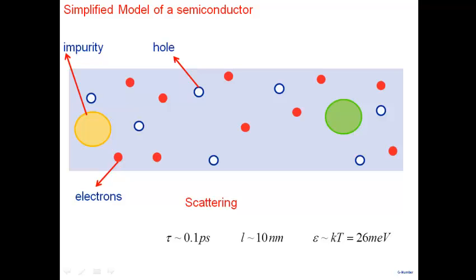It's totally random. Okay. So that's the picture that we have. So if I draw a line here, a cross section here, and suppose I'm interested in current, I've not applied any voltage here, I would expect on an average the same number of electrons which go from left to right as the number of electrons which go from right to left, right? On an average, there's no reason from symmetry to expect that more electrons are going right as compared to more going left here. So on an average, if I draw a line here or draw a plane, I would expect that net charge crossing this particular boundary is 0.